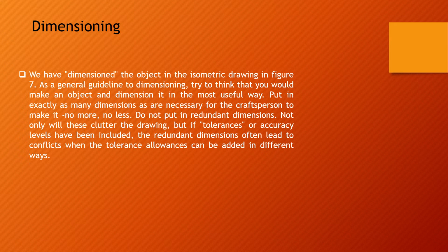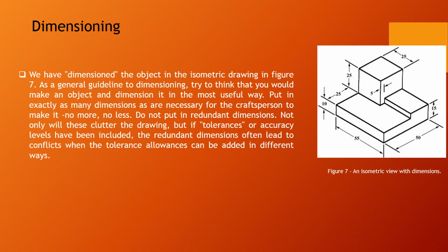Do not put in redundant dimensions. Not only will these clutter the drawing, but if tolerance or accuracy levels have been included, redundant dimensions often lead to conflicts when the tolerance allowance can be added in different ways. You can see it in figure 7, an isometric view with dimensions.